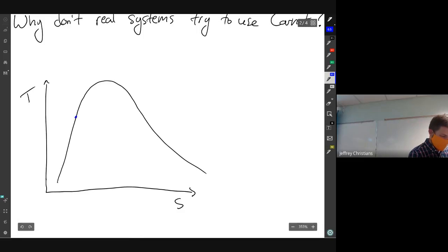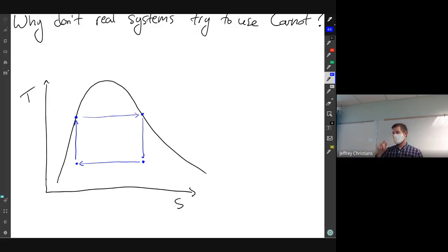So we'll draw the version that we have done before, say we did something like this, where we're going between these 4 different points. We're going in a box, right? At the bottom, the horizontal arrow is a heat exchange. Then we have a compression where we go vertically up. Then we have another heat exchange, horizontal, then a turbine, which is vertically down.